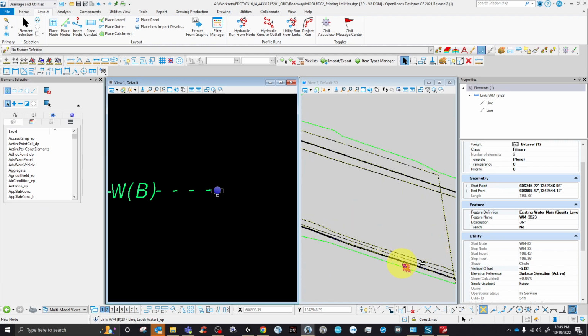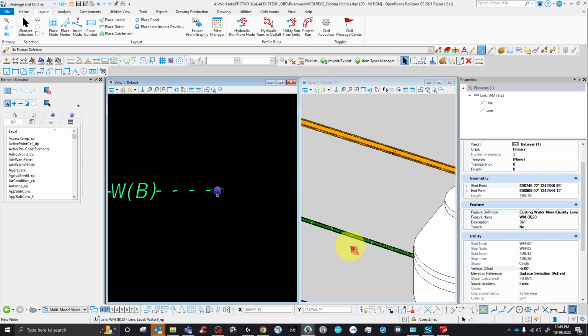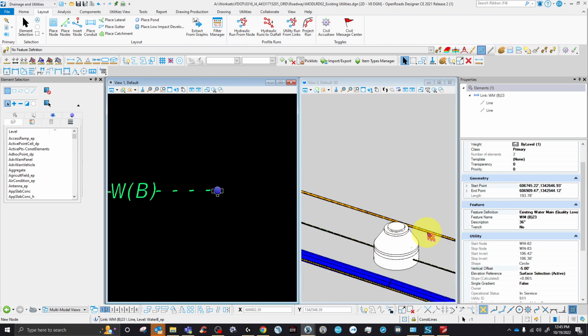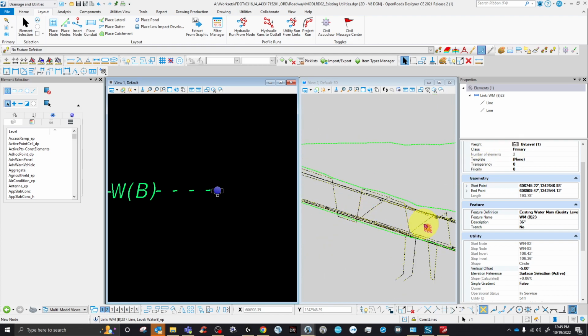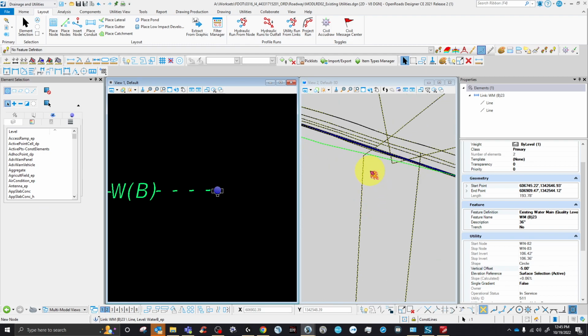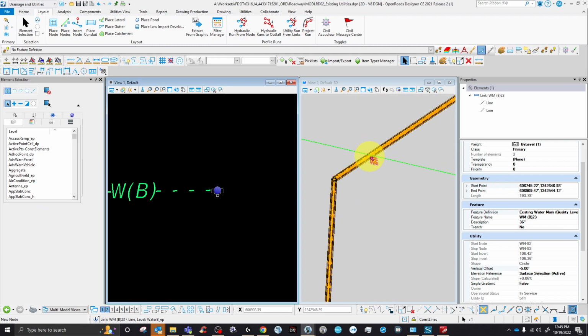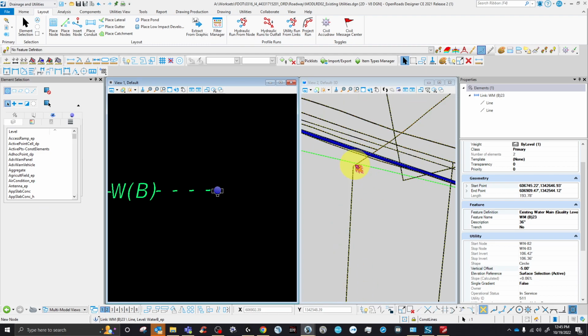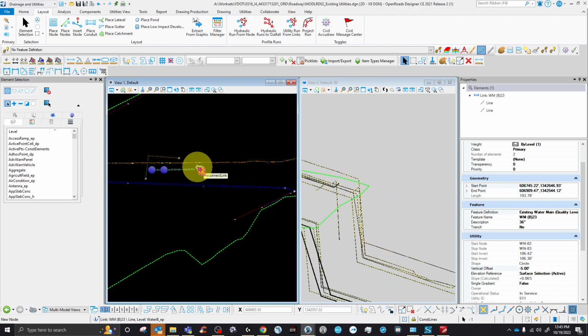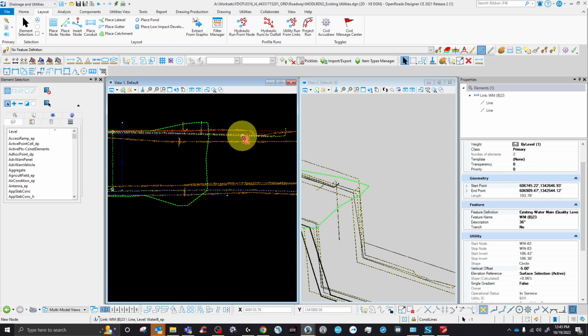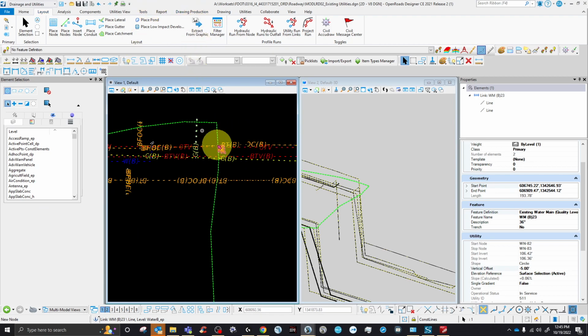As you guys see, I already modeled all these here. We have water main, this is sewer, usually green. This is a gas line. What else do we have here? This is some cables, utilities also. And I already told you, if they are funky like this, that means the elevation changed. It changed because we are outside the DTM, so there is no more elevation. It's just going to go to the ground. It's the same thing here, because I have them extended outside the DTM. Just remember, the tool only models within the DTM. Anything outside the DTM is just going to be gone.